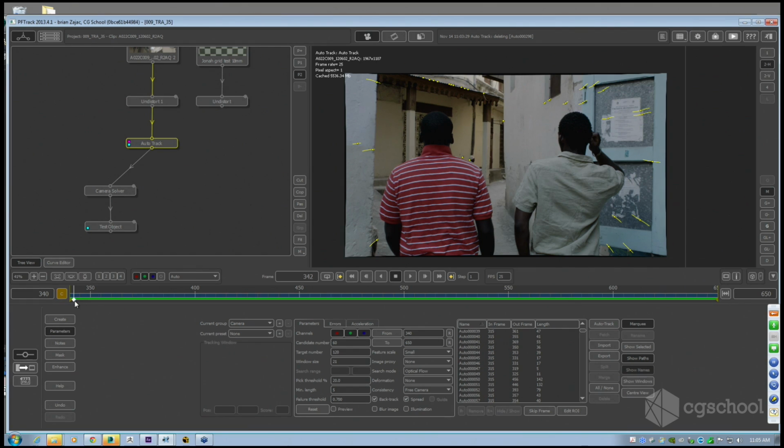So for me, the most detailed way of tracking this shot would be to delete all the points within the characters manually. And I know it's only about 200 frames, and I can do that, I think, in equal time, if not faster than creating that mask. And I think the results are more accurate because you're deleting very specific points. It's a preference, you can do it either way. Some people create really complex roto masks and then import those and have that separately.